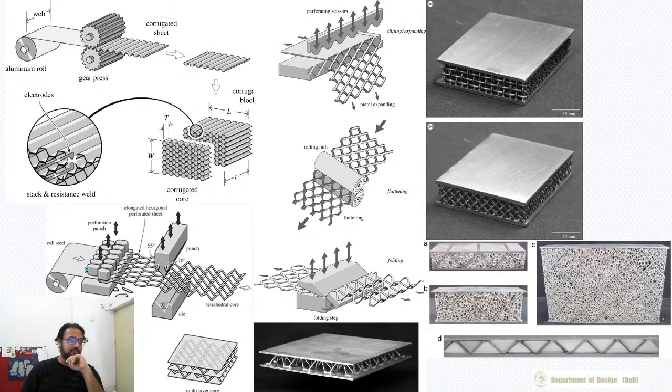There's another way of doing it from sheet metal. You make something like this, you punch holes and you bend it at the right locations, and that bend you could sandwich between two sheets like this, and you would get this kind of corrugated, I think it's called a sandwich structure. So you can get this kind of structures, and you could do a little more than that. There are some operations where you would fill the cavities with foam, aluminum foam, or other kind of foam like ceramic foam, to enhance, let's say, the thermal properties of the material, or acoustic properties of the material, or even the strength of the material. So this image shows you that. This is the direction, the advanced side of all of these things. It's very interesting to see such things, right?